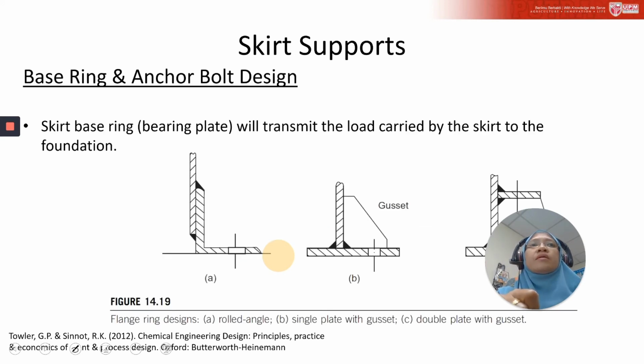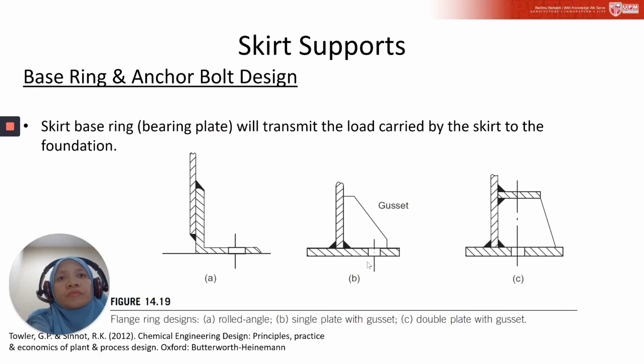And then, beside the skirt, the main skirt shell, the loads carried by the skirt are also transmitted to the foundation slab by the skirt base ring, or another name for it is base plate, a bearing plate, sorry. Before we go further, let me show you what is base ring, what is anchor bolt design.